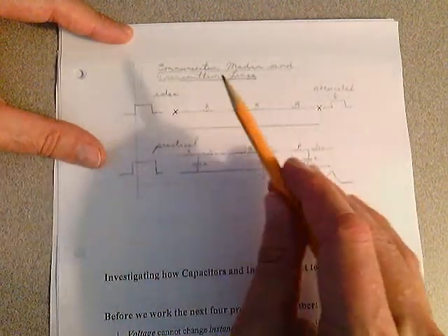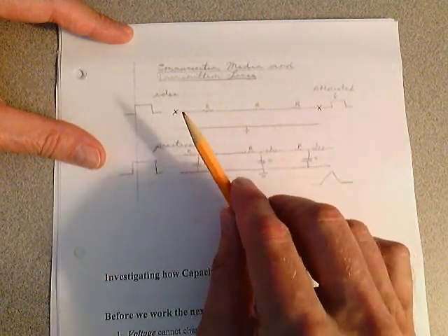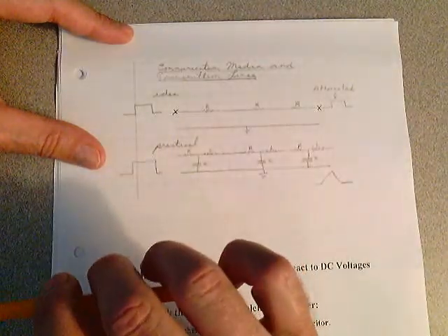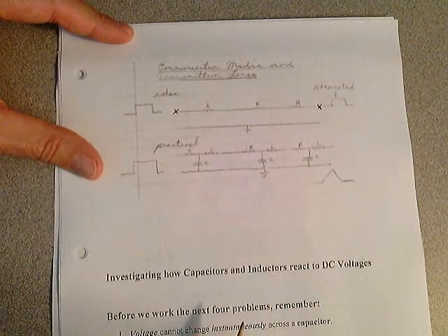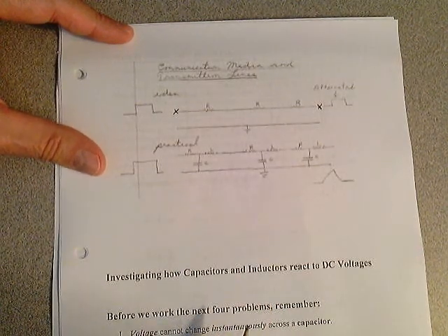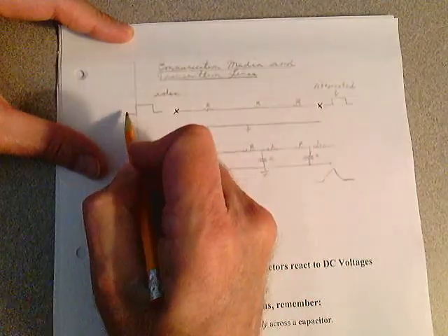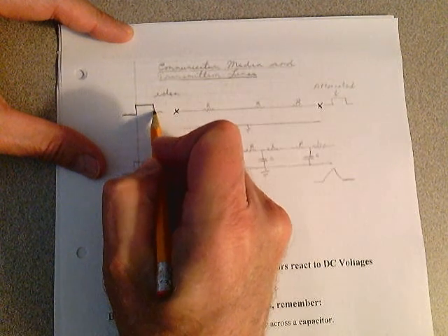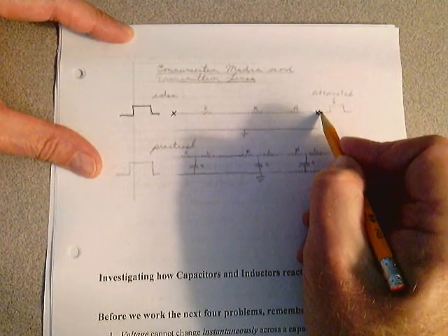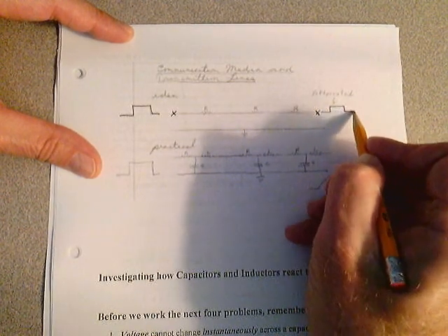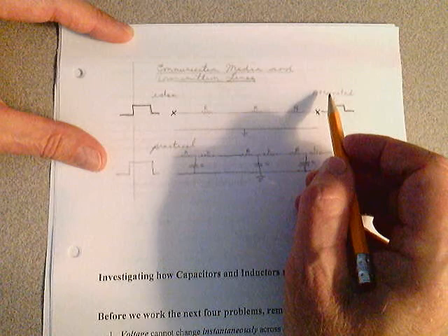But I want you to recognize that at the higher frequencies, you have to take into consideration our three passive components: resistance, capacitance, inductance. From this point to this point, if it's any significant distance, measured in thousands of feet or miles, there is resistance. So if you have a pulse, we'll just use a pulse from 0 to 5 volts, and as it travels down this line, when it gets down to this point, you're going to have an attenuation or a weakening of this signal. So we refer to that as attenuation.